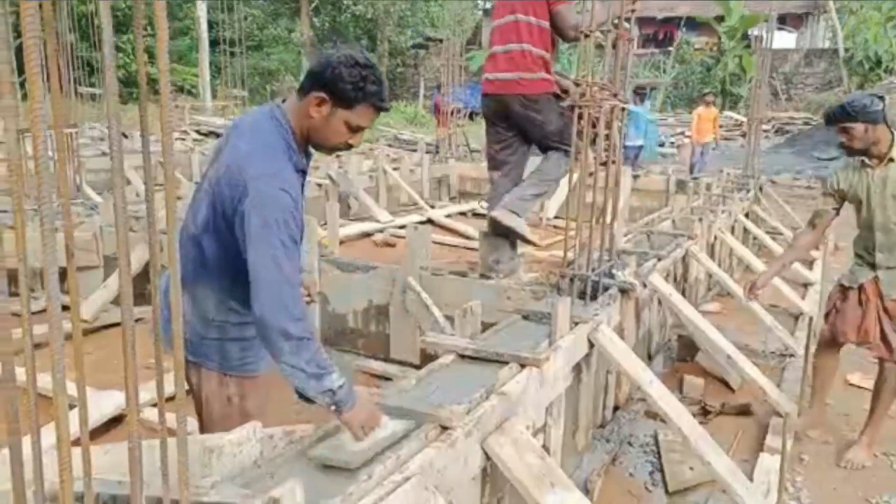So when the rubble concrete is constructed, the next step is to fill the basement with the earth. Approximately it will cost around 7,000 rupees on the assumption that you have sufficient earth in the plot itself. You don't need to purchase it. So what is to be done is, always get the house plot above the road level. You will always have excess soil or earth to fill. Cost will be minimum.